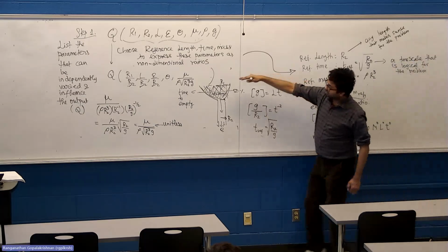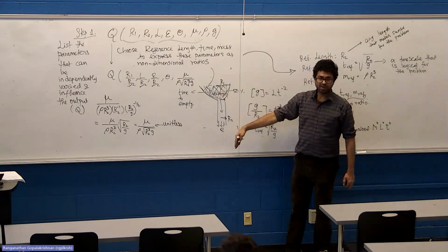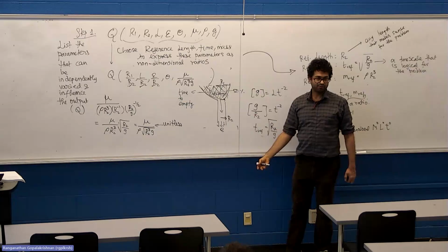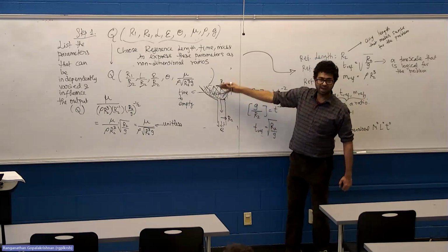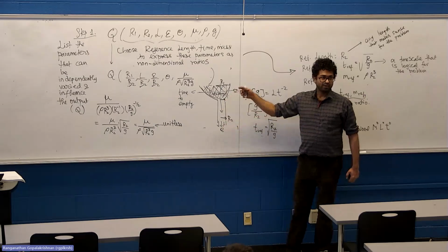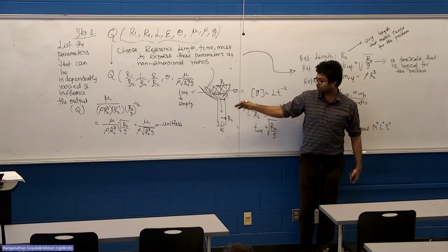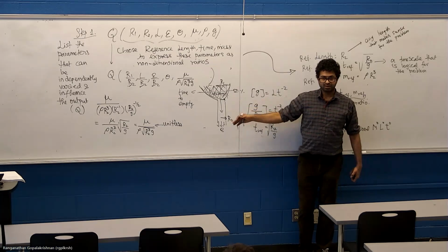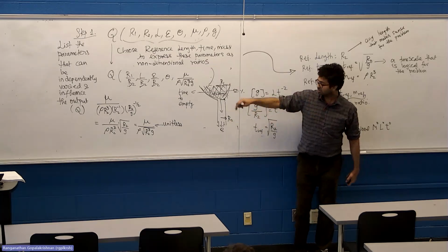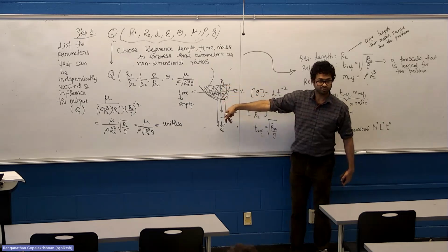If you fill the cup and then you watch it discharge, what is primarily driving the flow? First I said viscosity density, but think about it. It's gravity that's driving the flow. If you took this funnel to the International Space Station and did the same experiment there, would you have discharge? You won't have any because the gravity is not there to push it.